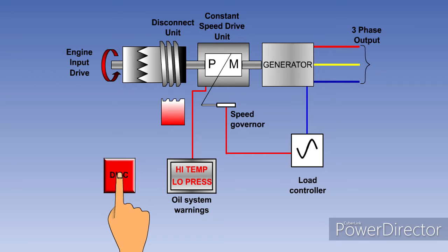The disconnect unit is operated by the selection of a momentary action drive disconnect switch by a flight crew member. This operates a solenoid, which causes a mechanical separation of the input drive from the engine to the constant speed unit. The mechanism requires the unit to be rotating for it to operate, so a disconnect should only be attempted when the engine is running. Reconnection may only be done manually on the ground, following shutdown of the engine.